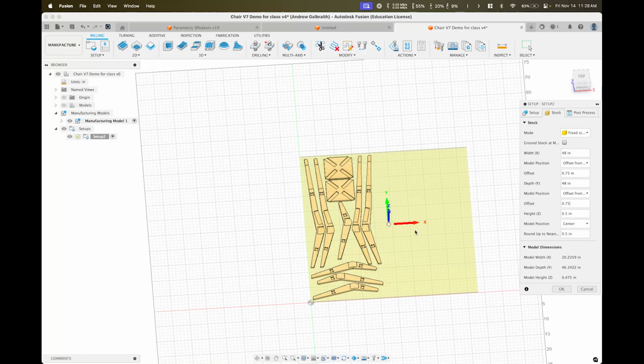Cool. Wait, so does that mean that your working space is 48 minus 1.5? What's that? Your working space for cutting? Yeah, you have slightly less than 48 by 48 because you need to have a border spaced around of 3/4 of an inch, just to allow for any imprecision with the setup of the CNC.